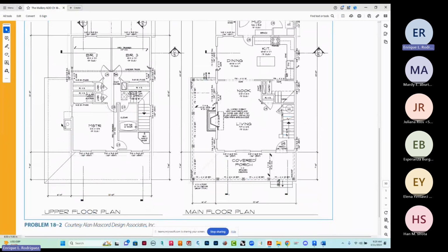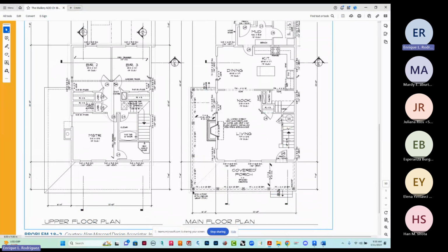And we also have a big porch going out in here. Now it tells you this porch width, and by the way, this is only measuring to the center of the columns. I want to measure to the outside of where my deck is going to be. So I'm going to make sure that this front porch and the side porch are the same width as opposed to what they give you here. The reason for that is because I like a cleaner condition for this hip set right here to hit right on the corner right here.